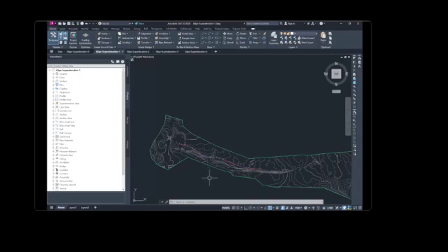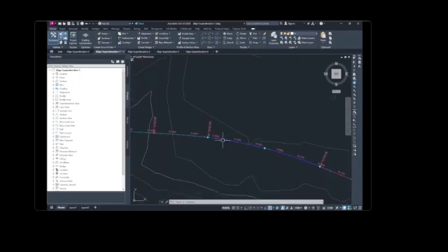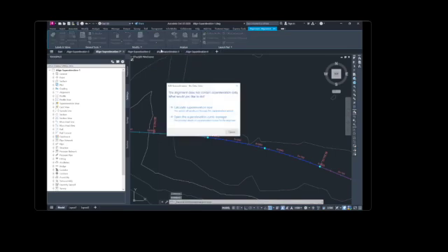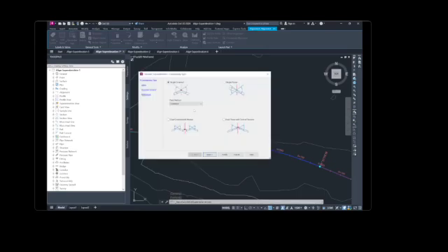We're gonna open Align Superelevation 1. Select the Alignment tab, Modify panel, Superelevation drop-down, Calculate/Edit Superelevation, and then click Calculate Superelevation Now. And then we're gonna select Undivided Crowned, and then in the pivot method list, select Center Baseline. Click Next.